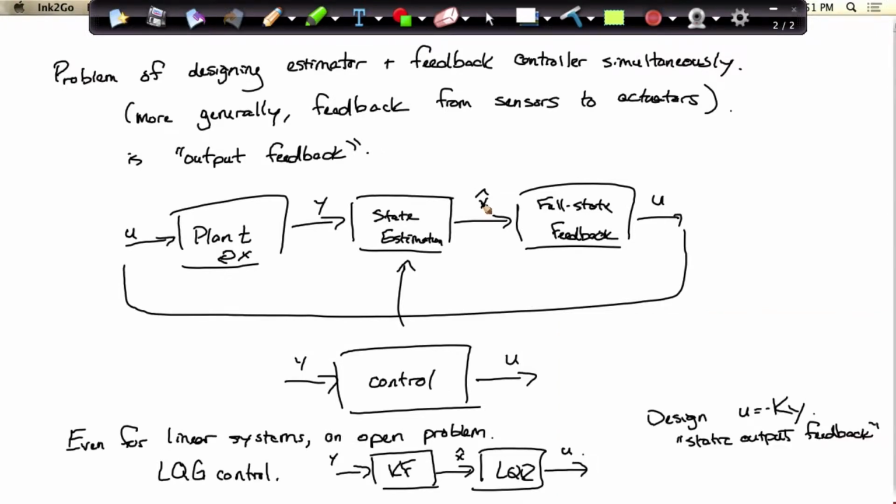So I think ultimately, when we get good at robustness, controllers that are more like this will pop out. Now, of course, an output feedback controller that is allowed to have state is a superset of the static output feedback. So these are always going to be better than static output, or at least as good as static output feedback. But somehow I just feel like we're putting artificial requirements to estimate state and have a dynamic model into our systems that don't need to be there.